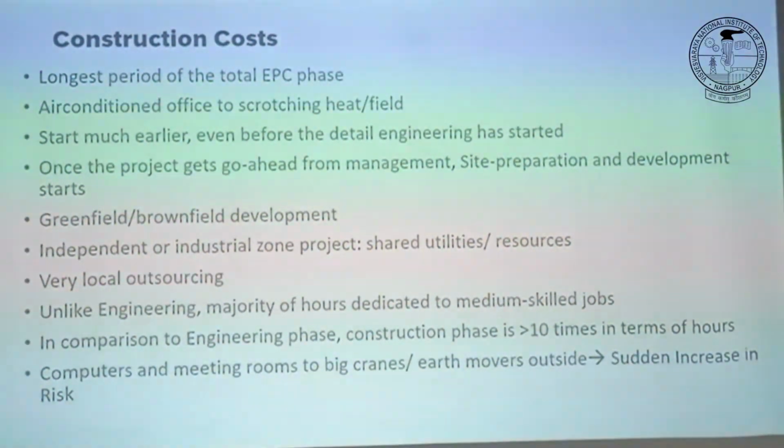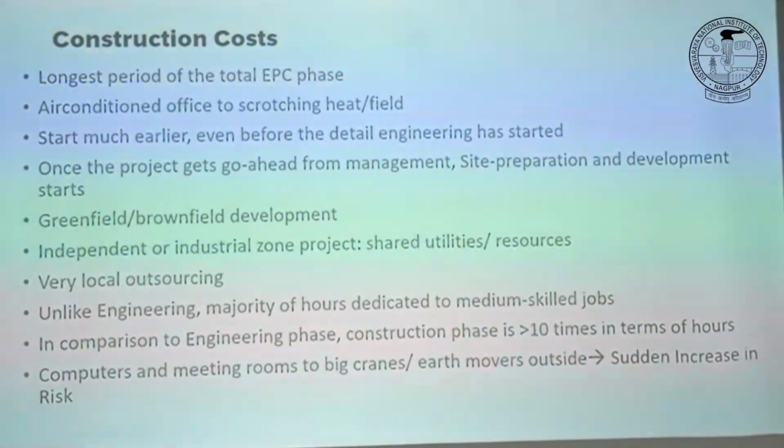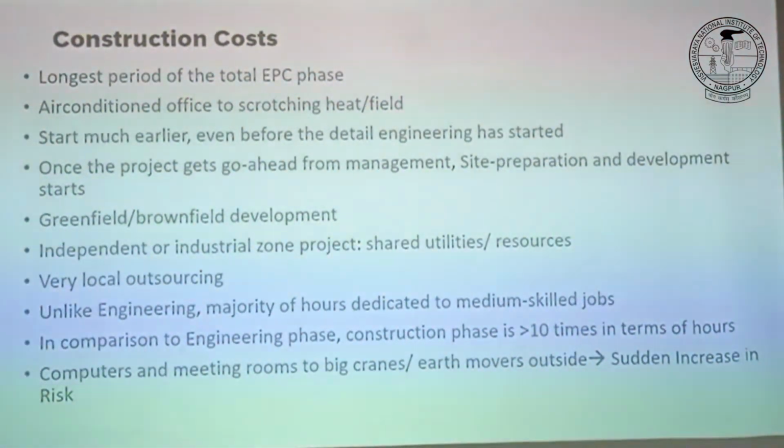you start the production. So you do conceptual design in 2 weeks, 2 months maybe, basic engineering in less than a year. You do detail engineering in maybe 2 years, somewhere around 3 years, 2.5 years. But in this detailed design, you already have the construction start. And the biggest period is the construction. Sometimes it takes 2 years, 3 years to build your plant.